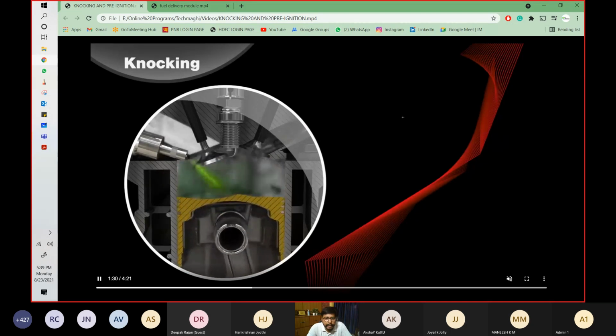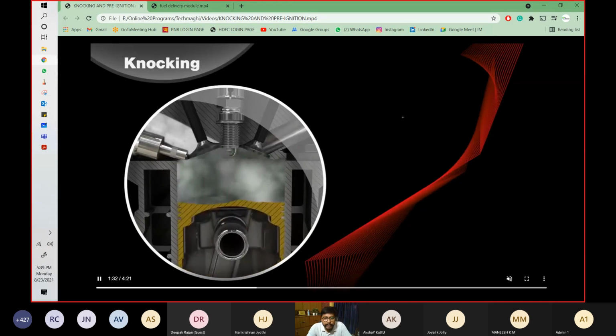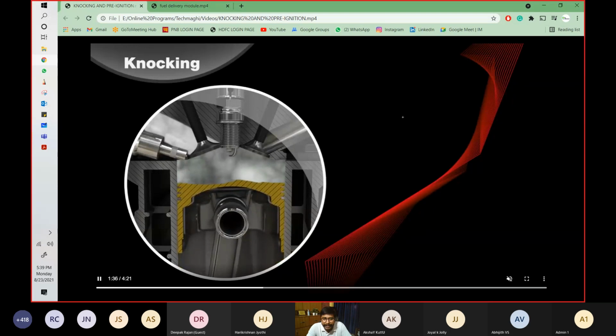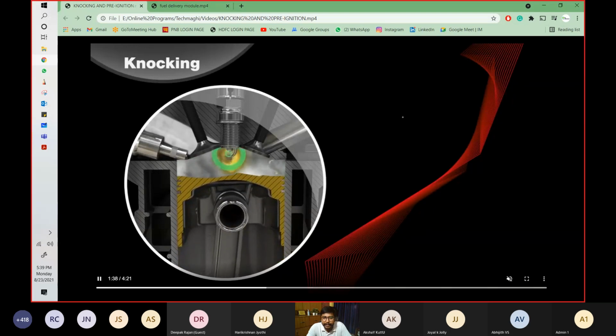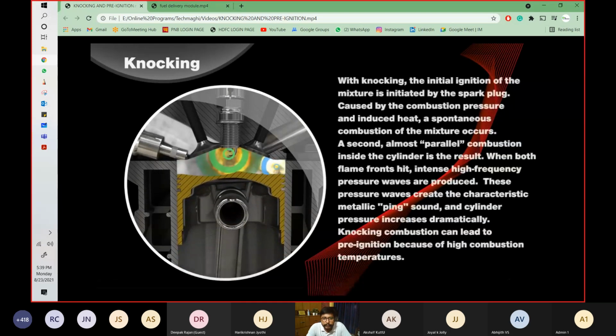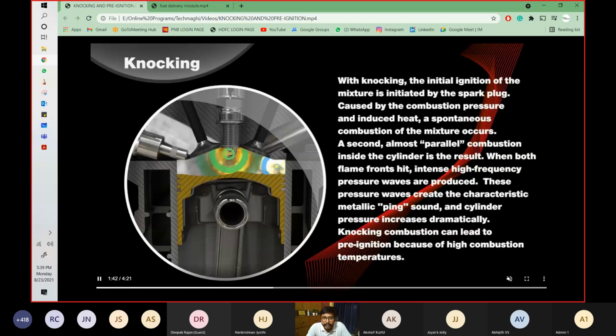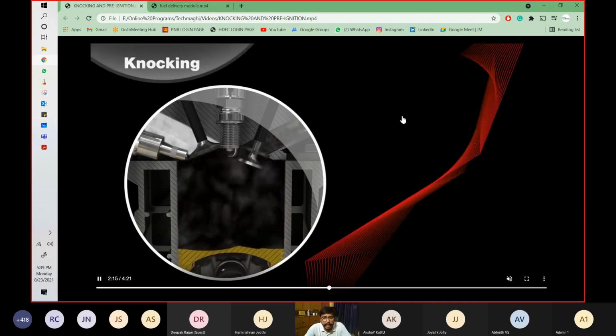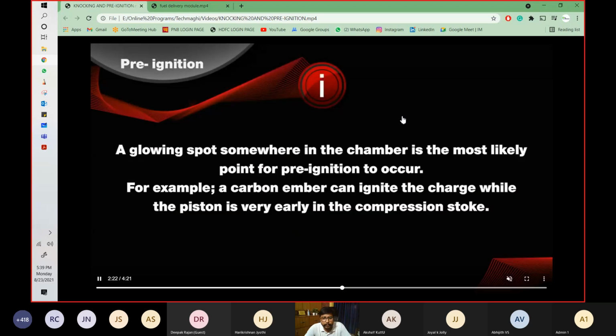This results into the mixture of the exhaust gases inside the combustion chamber with the intake. When the intake happens, it should be a fresh one. It should not be mixed with the exhaust. But in knocking, the exhaust emission will be mixing with the intake, and this will lead into disturbances into the normal cycle of operation, and this will cause knocking.